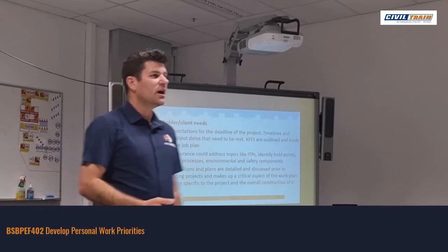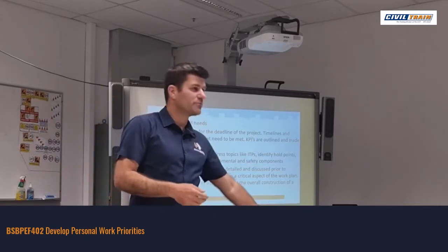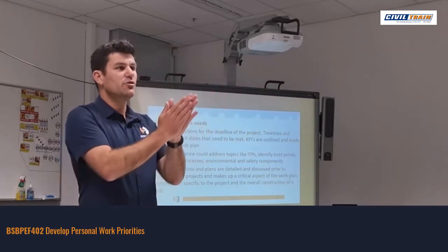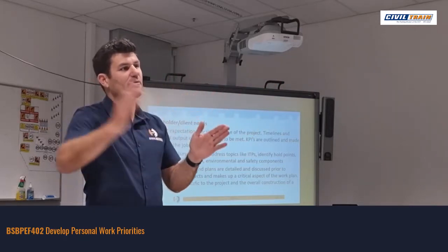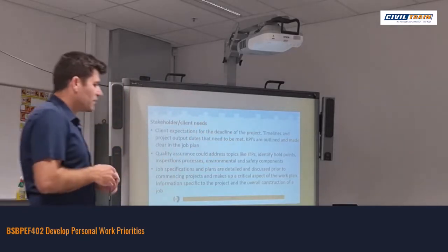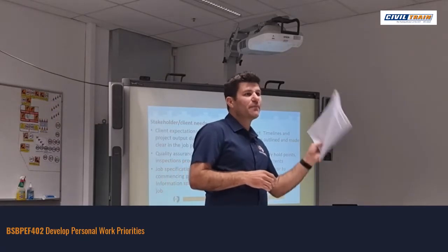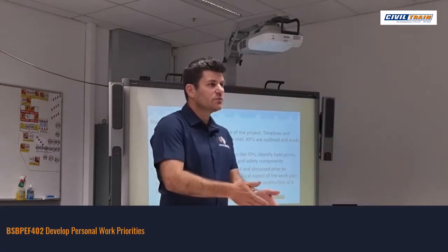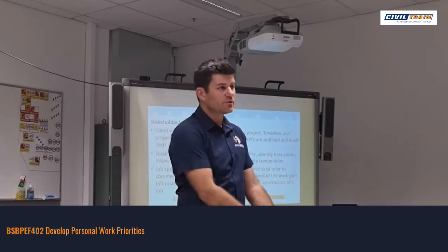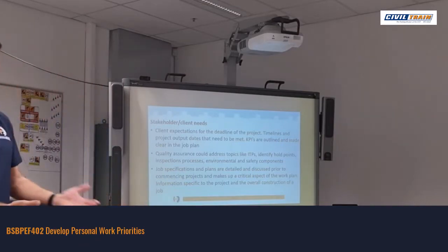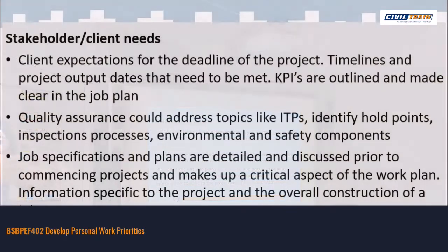All of a sudden you might need to create an ITP from your specification to identify those key areas to ensure that your works can happen in that progression. No doubt you're probably already familiar with that. One thing they always talk about here is compaction testing and soil compaction. If we do any works, we can't then start building on top of that until the results come in to say that we've achieved our pass marks to continue with construction.